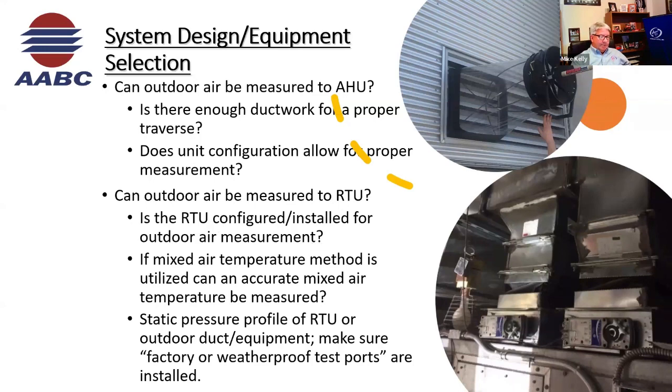Well, some days when it's 10 or 15 mile an hour winds, they call off the outside airflow testing and commissioning because it's going to affect your readings. Sometimes they've asked us to build tents on the roof around them. I don't like any of it, but that's what the owner wants, and that's the only way we're going to get true outside air.